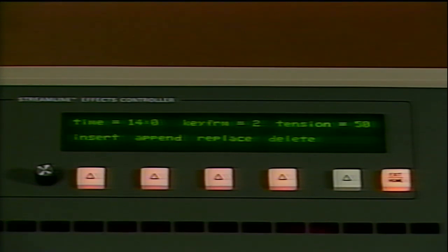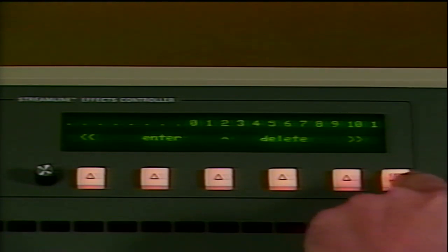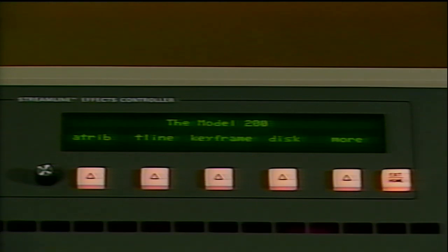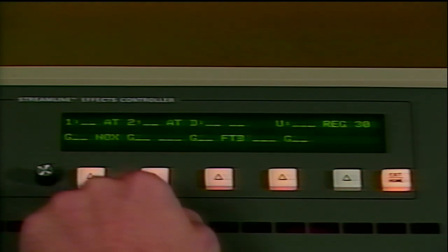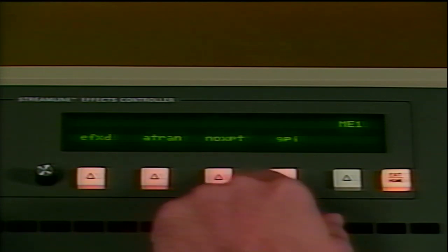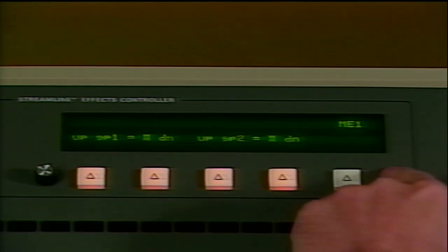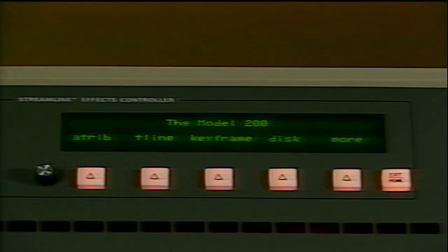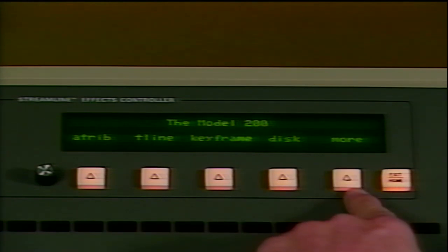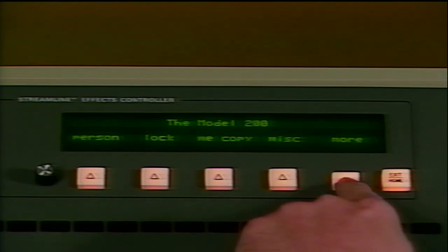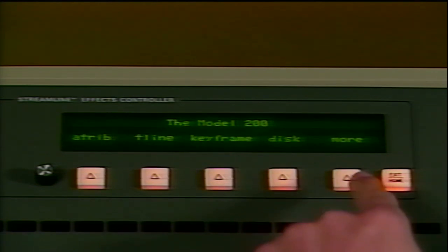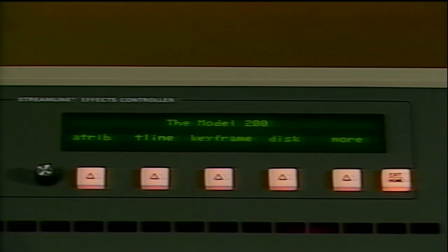The 6th push button, Exit Home, is used to return to the previous menu or go directly to the top-level Home menu. Holding down Exit Home for half a second returns the display directly to the top level or Home menu. The soft push button labeled More, found in some menus including the Home menu, toggles the display to show additional menu selections available from the current menu level.